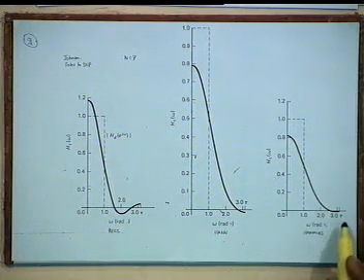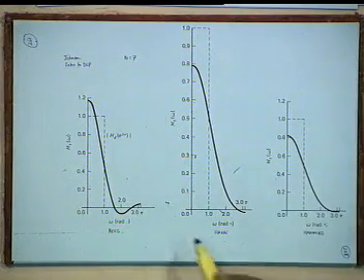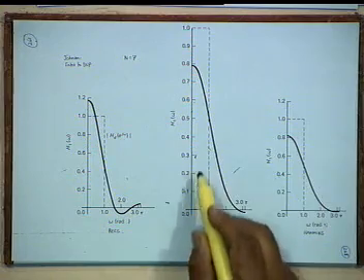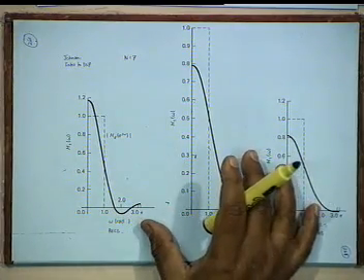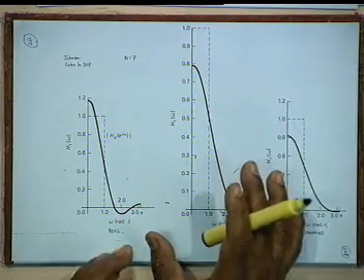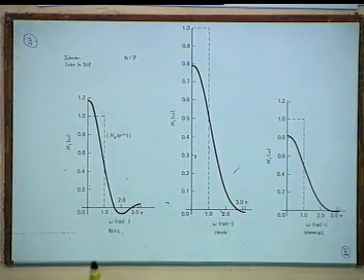So, if this satisfies your specs, one should not be unduly enthusiastic about Hamming, because in Hann the scales are different. Okay? This is not the type of plot that you should make. You must make the scales the same, normalize the maximum amplitude to 1, then compare. Okay? Then compare and measure or weigh against your tolerance scheme that is specified. Then you decide which we shall use. If Hann suffices, then you need not go further.